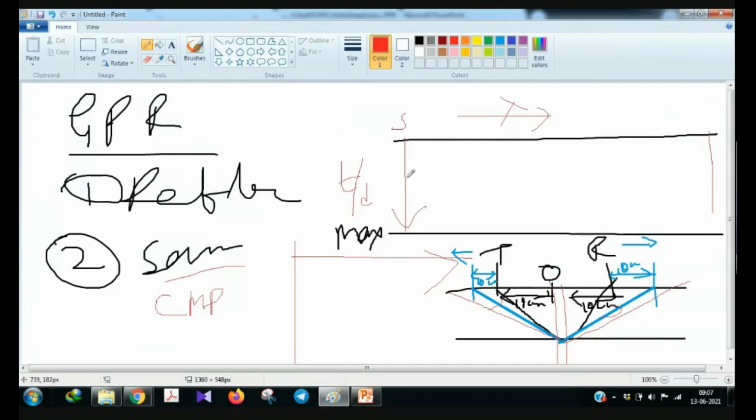Along the offset you will find several high amplitude reflections and several low amplitude reflections, and you will have a 2D cross section. But from the sounding, you can find the velocity of the subsurface, because velocity is very useful. When I am producing a result, that result should be in depth. But here you have the result in two-way travel time, T, let's say in nanoseconds, and X is the offset distance.